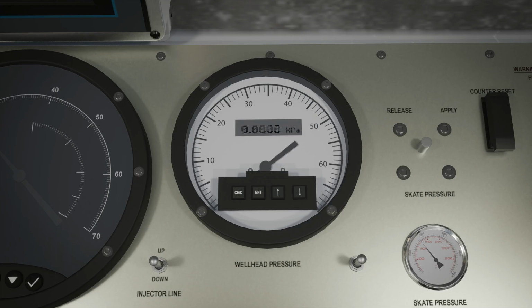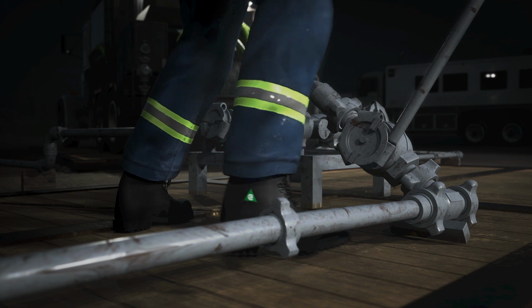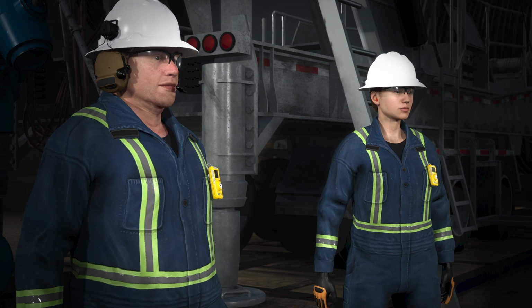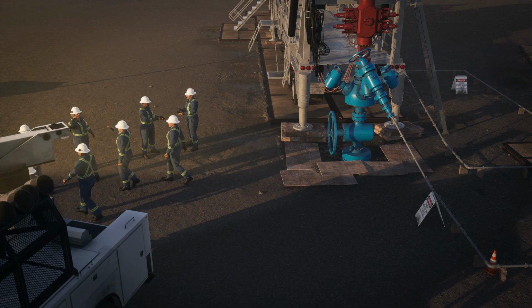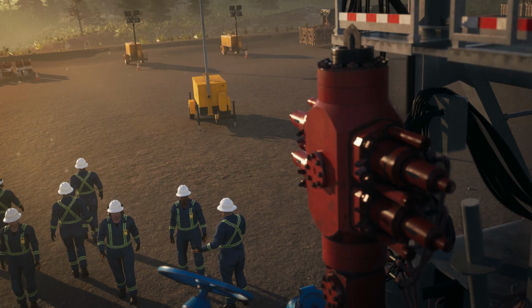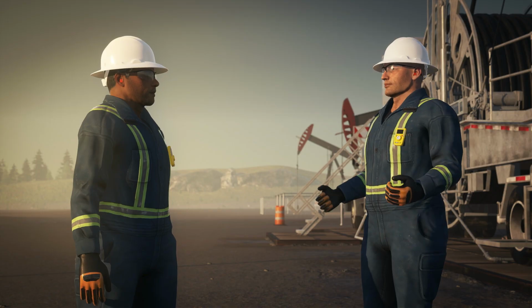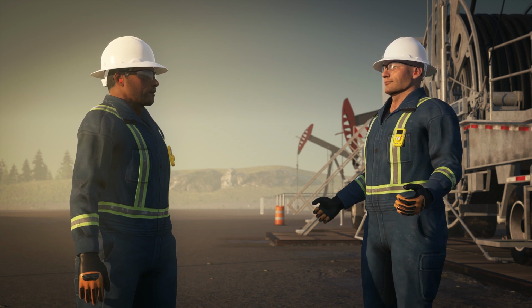They then bled off the pressure and pressurized the line to 24.1 megapascals. Similarly, they closed the new valve and confirmed that the pressure held, indicating a successful high-pressure test. When the day crew arrived, the night crew quickly briefed them on the issues and that they had been resolved. All that remained was to depressurize and remove the test bar. The new valve was mentioned, but no formal documentation for the new valve was provided.